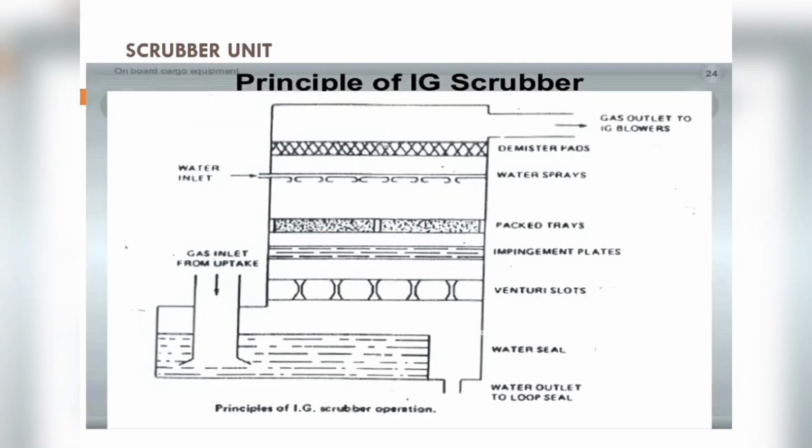If too much black is there, it's a good idea to tell the engine room. They can increase the pressure on the scrubber tower, so that too much black soot doesn't come out, especially in the initial stage. Is it okay to discharge this water directly without treating? That's right, it's not pollution. It is acceptable. So when you see this while taking a round, it's a good observation.